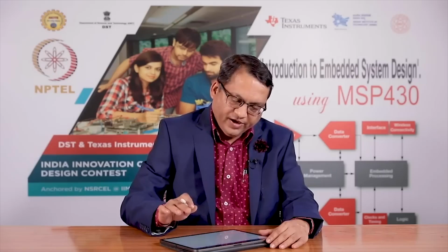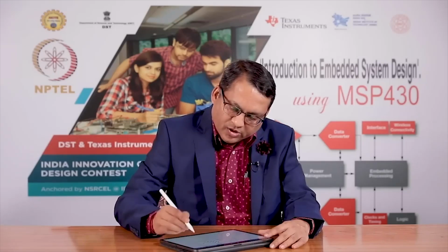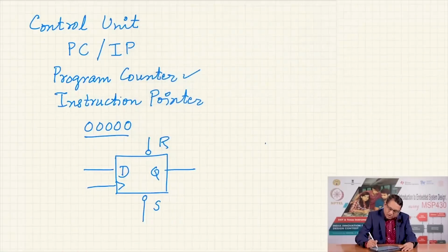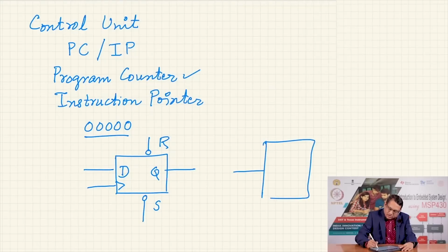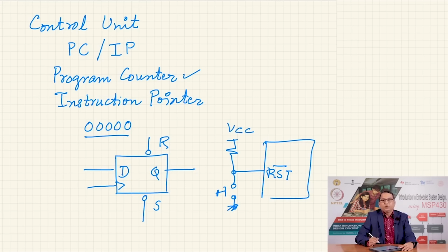And usually the way to do that is on these pins RST bar, you would connect a switch. So, every time you want to assert a user reset, the user simply presses this switch, it pulls the reset pin to ground, this resets the internal circuitry, and when the switch is released, it would allow the circuit to reset and then it will start performing its expected task.